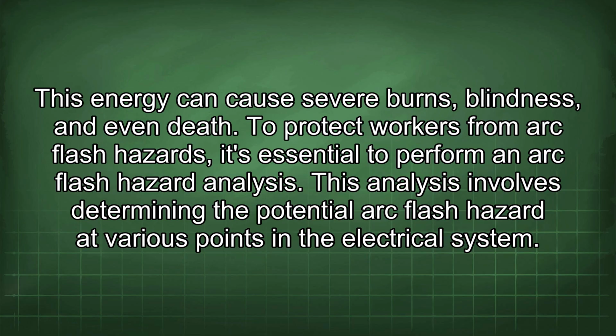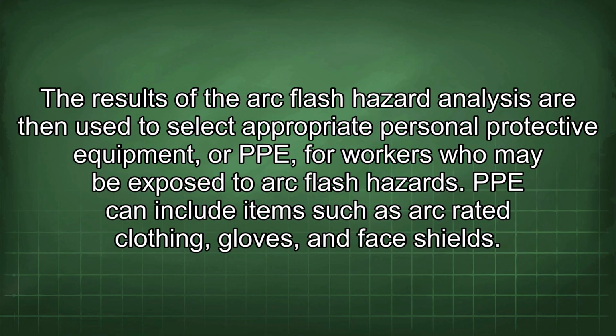To protect workers from arc flash hazards, it's essential to perform an arc flash hazard analysis. This analysis involves determining the potential arc flash hazard at various points in the electrical system. The results of the arc flash hazard analysis are then used to select appropriate personal protective equipment, or PPE, for workers who may be exposed to arc flash hazards. PPE can include items such as arc-rated clothing, gloves, and face shields.